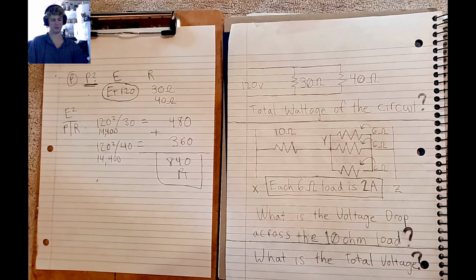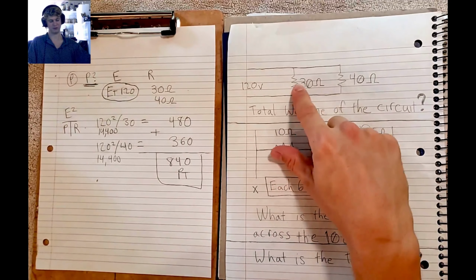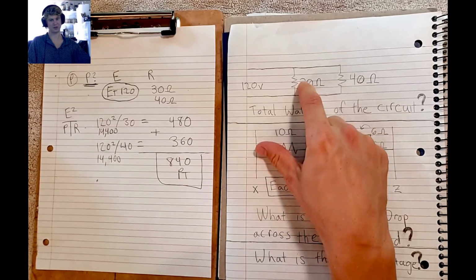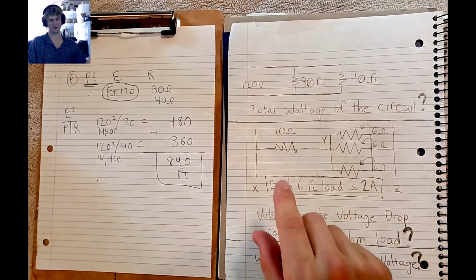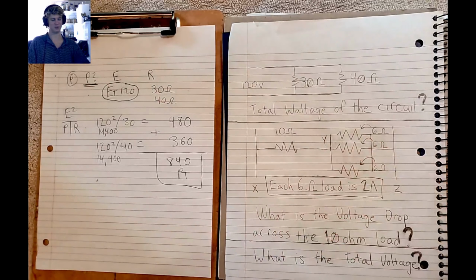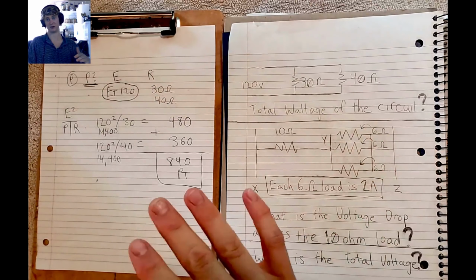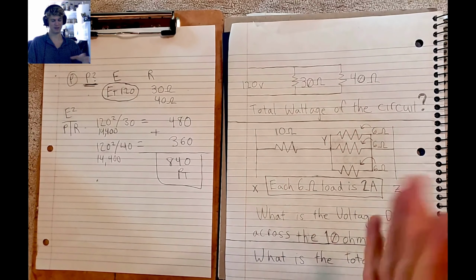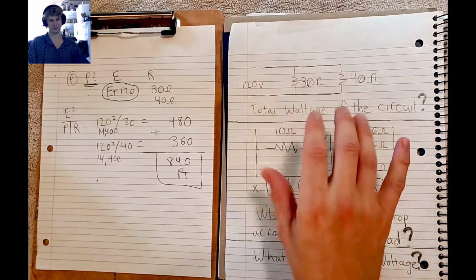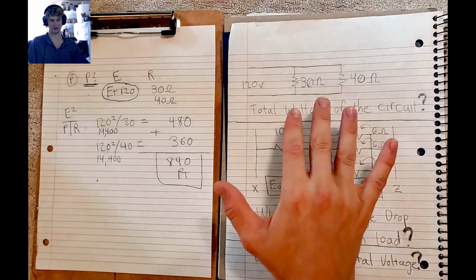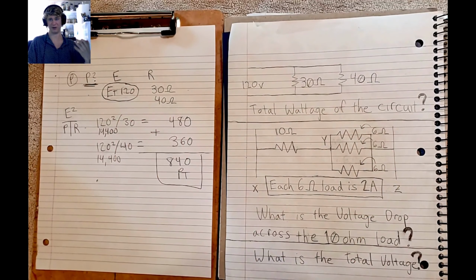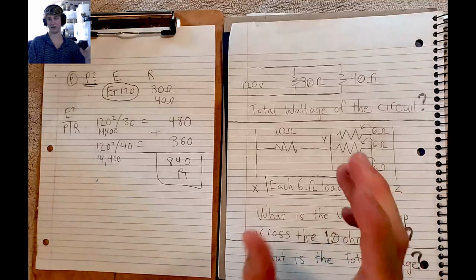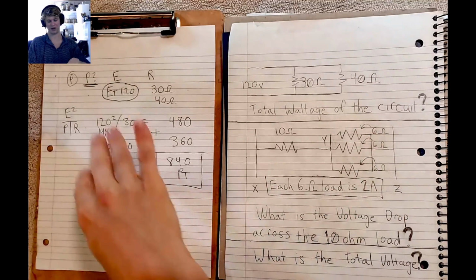In fact, we can actually see we got the more accurate answer, keeping the whole numbers of the resistances, and then separately finding out the power for each of them and adding those powers together. So this is one of those things where you got to know a certain time and place where you should use a certain method over a different method. In this case, avoiding solving for the total resistance actually saves a lot of time, and we can see we only took up about half a page versus before we took up about a whole page doing the same problem and not getting as accurate of an answer, plus a lot more math.